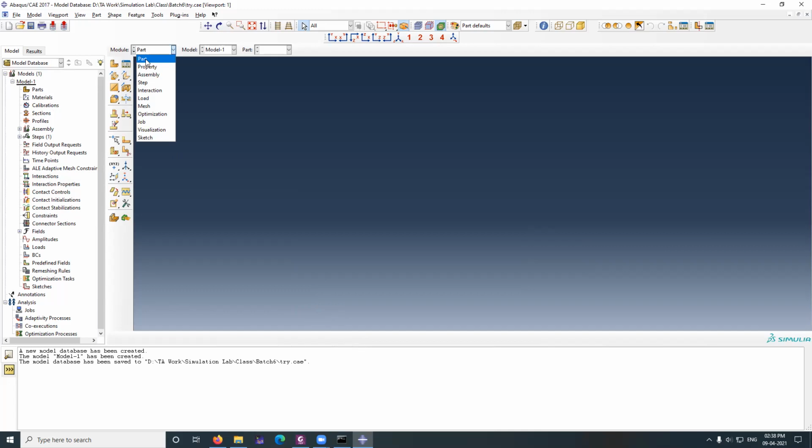Say for example, in module part one, we will create our parts. Workpiece we will create, tool we will create, then we will go to property, then we will give a material property, aluminum material property, to our workpiece. Likewise, then we will assemble both work and tool in this particular step. Okay, then we will do this final step. This is where you choose your physics. So basically we will go in order. Okay, so when we change property, then the tools here will change.